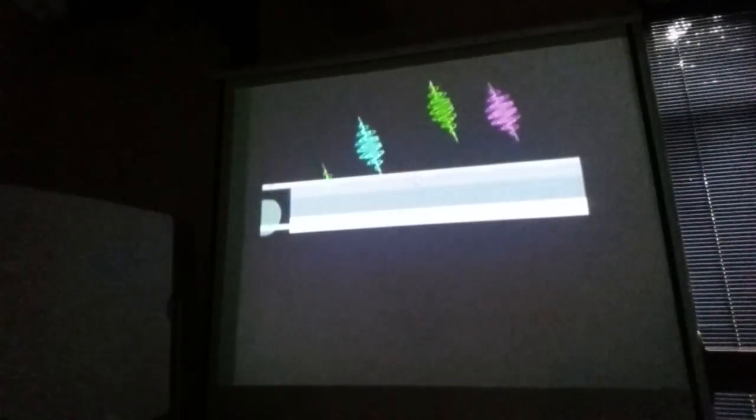In the junction, their energy can be absorbed by electrons and excited into the conduction band, leaving behind positive holes. But before these can recombine, the electric field in the p-n junction separates them. The electrons move toward the front surface, and the holes move toward the back. Then they travel through the load and around to the bottom of the solar cell.